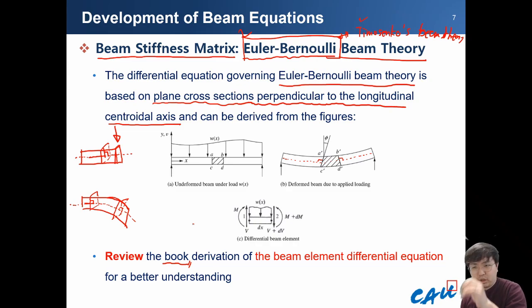Similarly, we obtain all the displacements at the nodal points. However, at some points we already know the displacement due to boundary conditions. So we finally obtain the solution after applying boundary conditions and solving the linear algebra equation, and then we can obtain the whole displacement vector. Similarly, the force vector is directly obtained by matrix multiplication between the global stiffness matrix and the displacement vector.